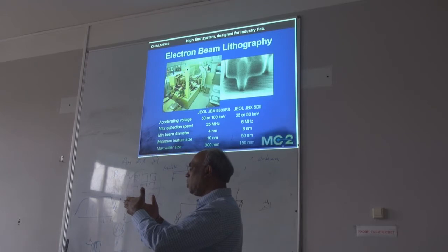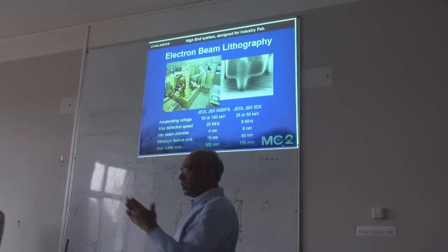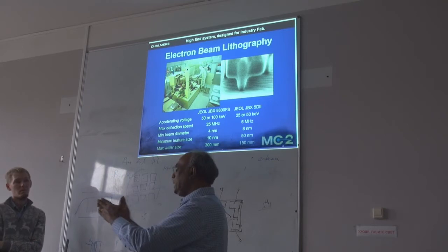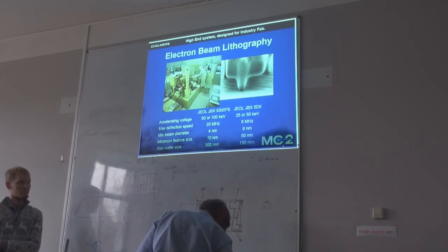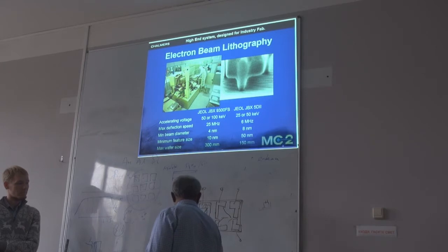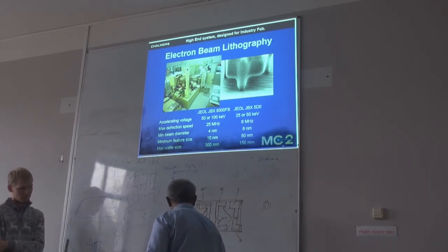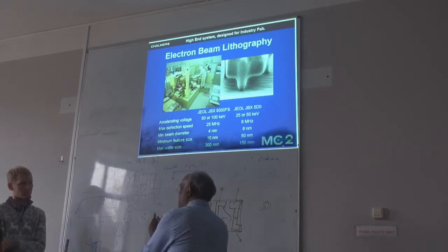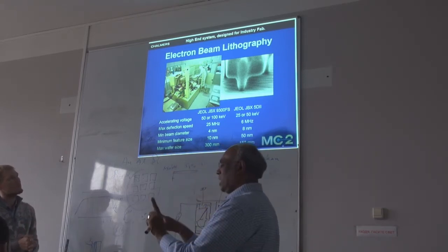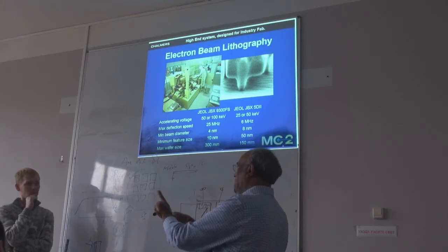But also if you want a smaller separation, there's something called oblique angle deposition. Suppose when you do E-beam like this, you are exposing this area, right? But if you do it at an angle like this, then you are only exposing this part, right? Yeah. So then you can do the next one from this side, so you can reduce that separation. So you can have something called angle deposition.